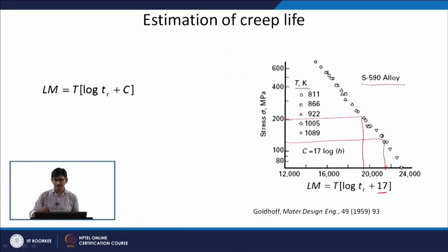So, all the temperature curves are plotted on one single curve here. You can see for different temperatures all are falling on one single curve. So, once I know the stress and the temperature at which I have to use this material, I can find out what the time to rupture will be.